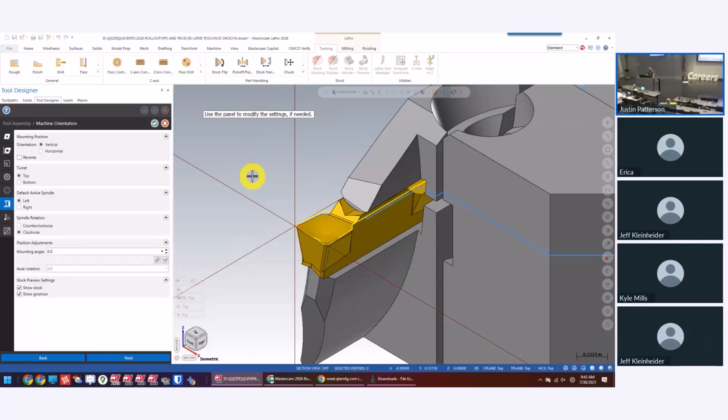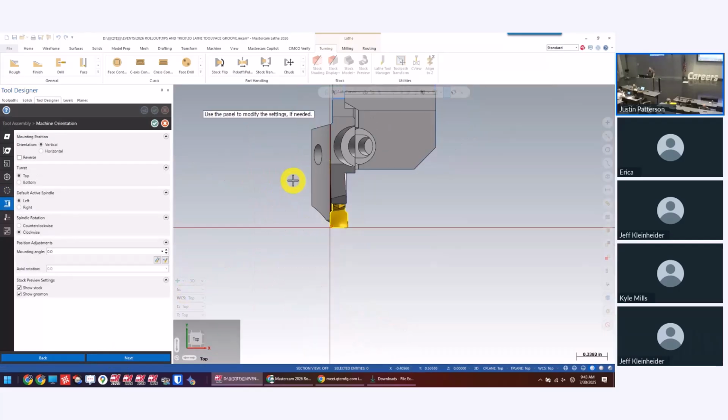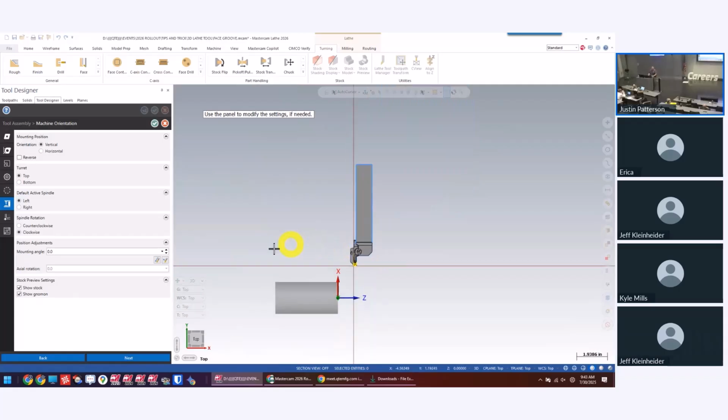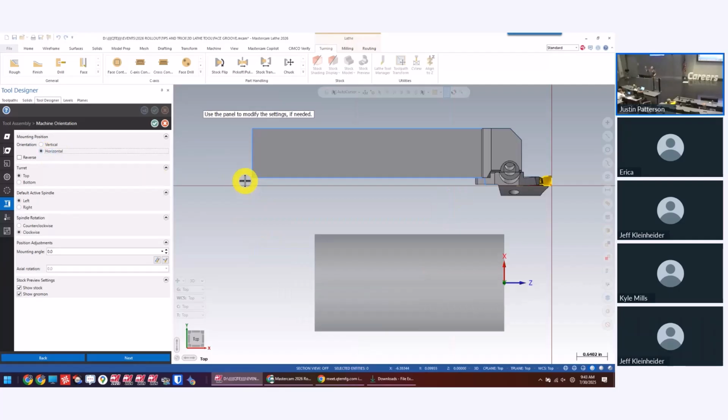Go next. Now here's the most important thing. If you're working with a standard turret machine, a Puma, Lynx, on a Doosan, Puma or Lynx, an LB, something that's got a turret mount to it, you want to align this thing how it's located in your turret. If you're a B-style head, a milling spindle, we want to put in here the orientation of how it comes at a tool change. Okay, so that's where you'll ever hear me reference that. It depends on what kind of milling, what kind of head mounting system we have here. So let's just pretend this is on a turret style machine. So I want to come in here. And in this case, honestly, it would be the same thing. They're both orientated the same.